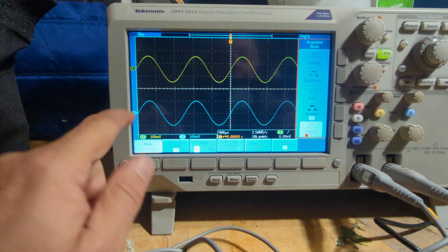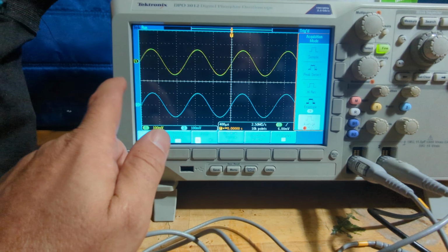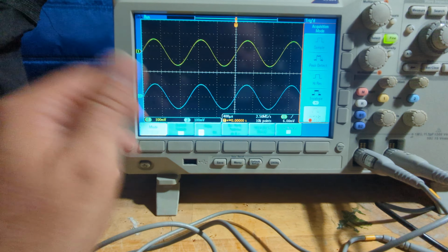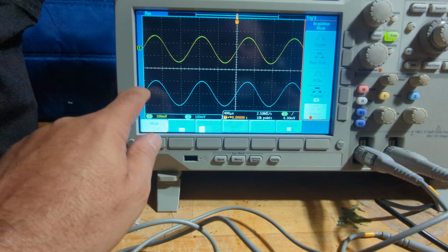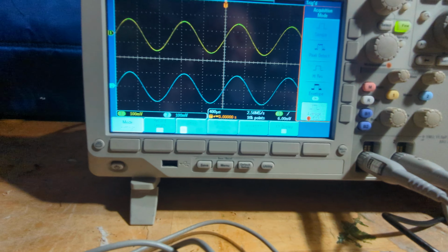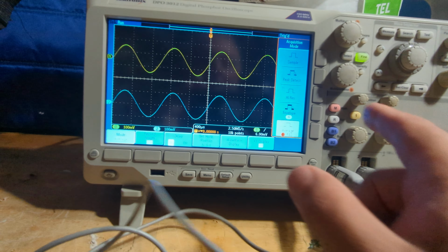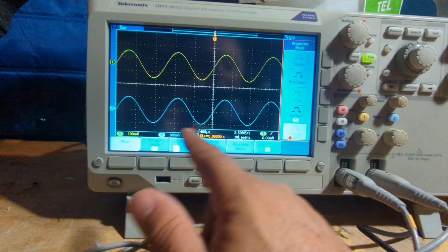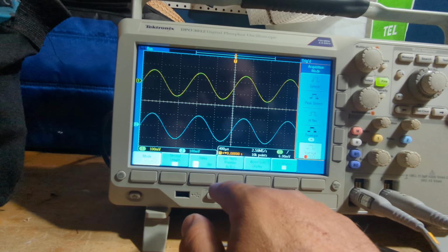What you have to understand is that it's reading from here to here every cycle, and so it's averaging that out. If you were to watch these waveforms, they would just continue on forever, but the display is going over and over the same period sample window, right?